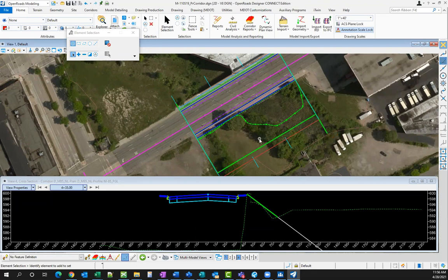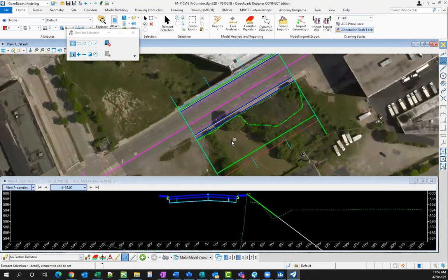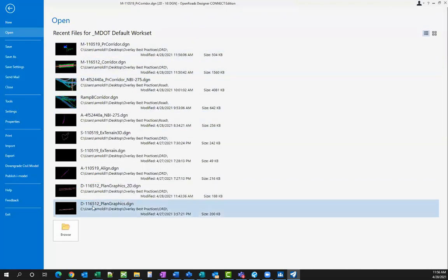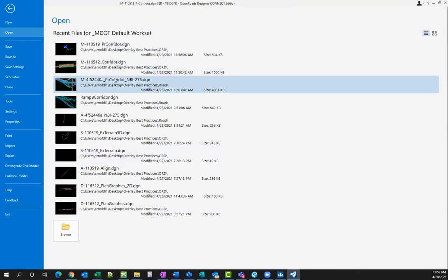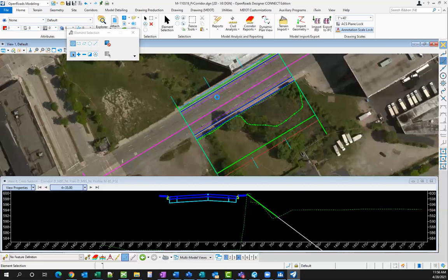The next thing that I wanted to talk about, it's something that Chuck brought up. It's pretty common where if you have a fill slope and your end condition is tying in, you have something goofy going on at your shoulder where your end condition is tying in way up here. That's not actually what you want. You actually want to daylight your material out to the end. And so I'm going to show that in a different project directory. I believe it's this corridor right here.